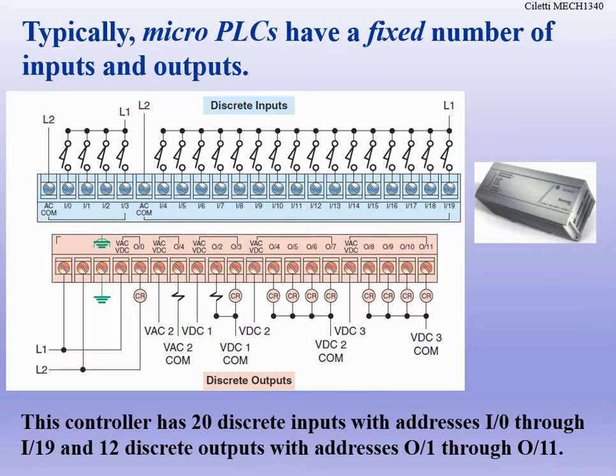So let's talk about the different types of PLCs. Micro PLCs are fixed PLCs. Those might be like our Siemens LOGOs, with a very small number of IO, and our Siemens 1200s, which are more fixed PLCs. Even our 1500s can be modular, but we use them as fixed PLCs. But if we look at the 315 that we have in class, that's our modular one. We can see that there are a bunch of different slots in racks in that case, versus our 314s, which were fixed, the original one. So just remember, we're talking about the number of inputs and outputs.